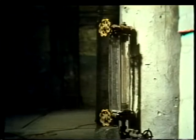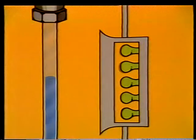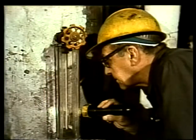Now, there are three common types of gauge glasses: tubular glass, flat glass, and multiple port. The tubular glass type consists of two gauge valves connected by a piece of glass tubing. A tubular glass gauge will often have a colored line on the back of the glass to make a clear fluid level easier to see. A second way of making the level easier to see is illuminating the gauge with a strong light. The light can be a permanently installed illuminator, or a flashlight can be used.